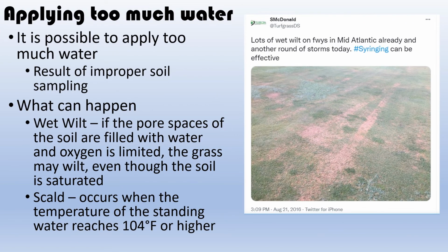So the question also arises, can too much water be applied? And the answer is yes, it is possible to apply too much water. Primarily, this is the result of improper soil sampling. So you go out with a hose, and instead of taking core samples or using a TDR, you're just thinking, it looks dry, so I'm going to throw some water on it. And this is not always the best practice.